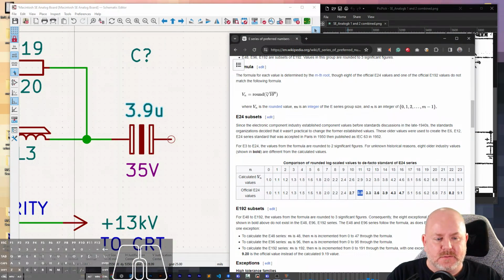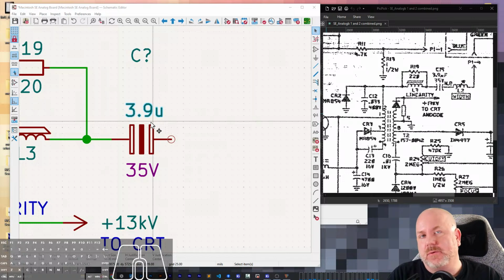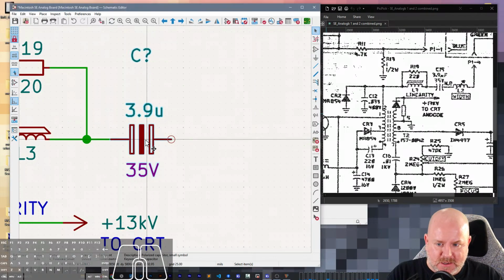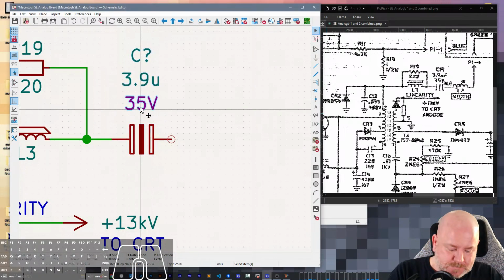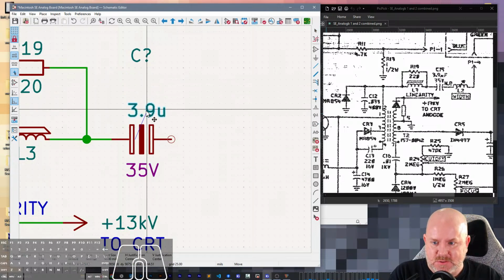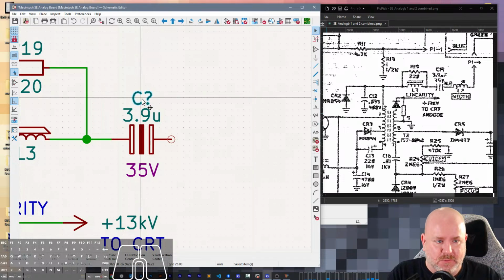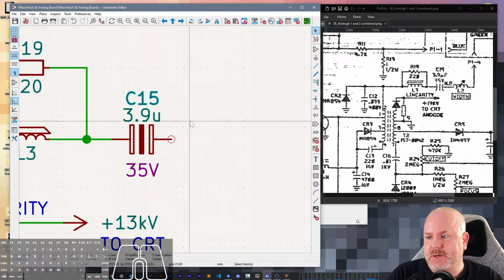You can get a couple of these values in a bipolar cap today, but they are maybe a fourth of the size. So their impedance is not the same, and there's no way they can handle the amount of ripple current that the older parts do.